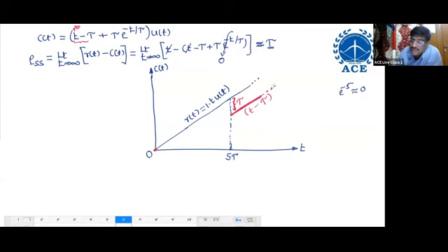This will be continued parallel to this. At any instant you observe, the difference is tau only. That's why we got steady state error. How much did you get? Tau. So the difference is tau only always. After 5 tau, you observe the difference between input and output, that will become tau. That is called steady state error. This is the line of t minus tau.